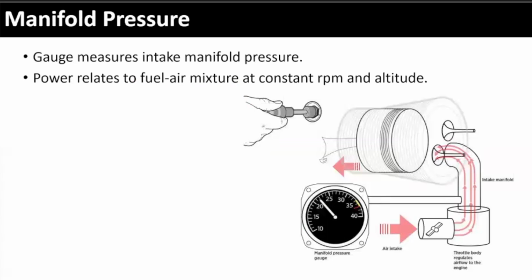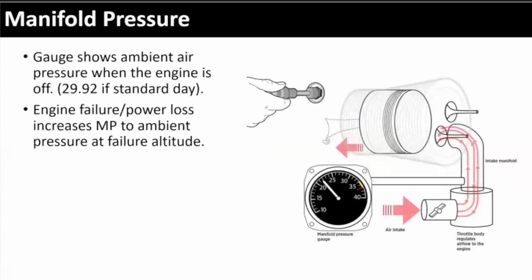We talked about manifold pressure. Talk about ambient air. We talked about higher altitude: your manifold pressure will just naturally decrease unless you increase the throttle. Because it's measuring the pressure across the manifold, what's it going to read when you're sitting on the ground and the engine's off?